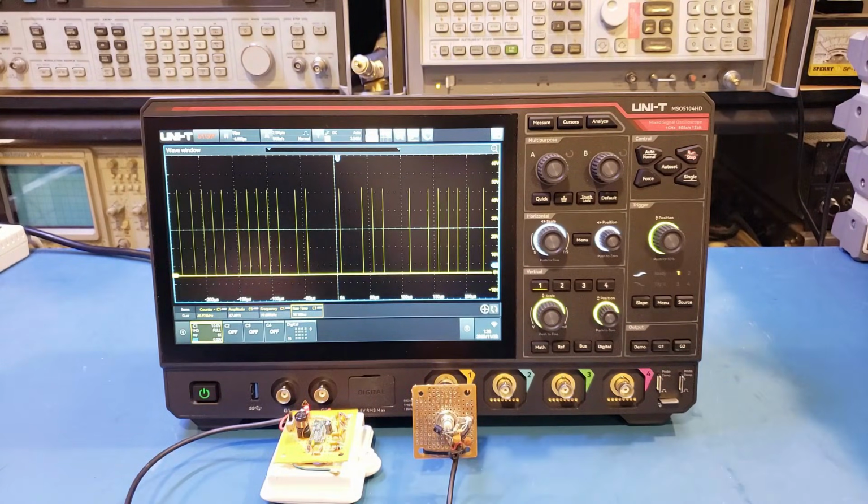To solve this problem, modern digital scopes often include the so-called segmented memory mode. The idea here is instead of using a single chunk of large sample memory, the memory is divided into smaller segments or frames. The main difference is once triggered, the oscilloscope will only fill the next available segment instead of the entire sample memory. Once a segment is filled, the oscilloscope will stop capturing and rearm the trigger until the next trigger event occurs. So in this way, even if the events of interest are few and far in between, you can capture all of them because the events will be individually triggered and captured into their own memory segment.